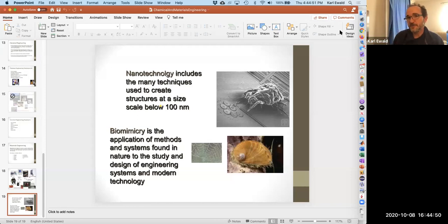Most chips are made through a really intricate process of using masks, deposition of material, and then etching and other processes. It's built up layer after layer after layer until you get to the complexity of a modern semiconductor structure. It's not done directly; it's done in mass.